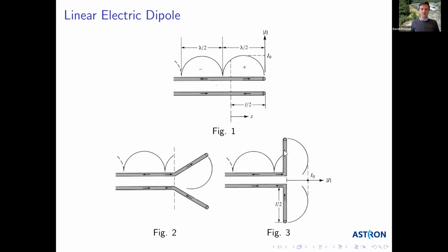And if you were to measure this in a lab, if you have a dipole antenna and a current probe, I would really recommend that you do this. You can actually measure this sinusoidal distribution on the dipole antenna. If you take the current probe and slide it along the length of the dipole, you'll see that the current approaches 0 at the end and becomes a maximum in the center if it is at a half wavelength.